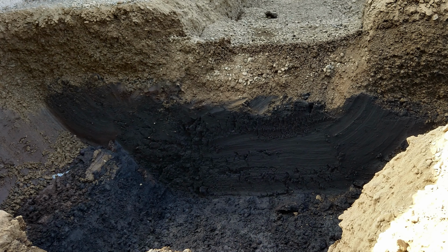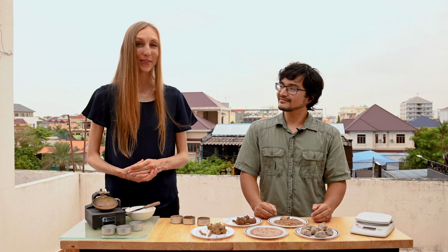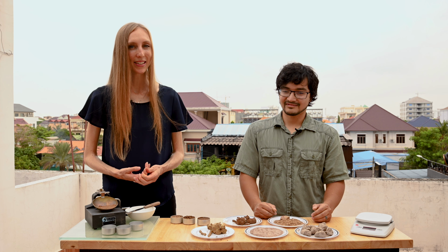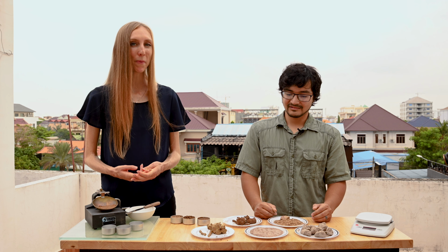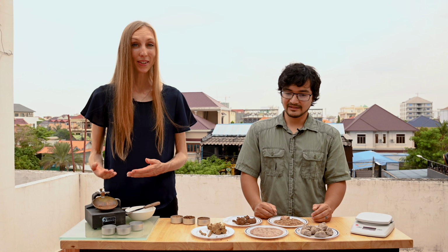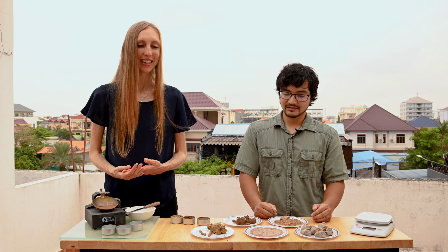We can also encounter a subgroup of soils called organic soils. These are typically fine-grained and formed by decomposing vegetation. They usually are a dark layer in your soil stratigraphy. So their presence can lead to unsatisfactory soil performance, including low soil strength and excessive settlement. So it's really important to try, while you're in the field, to be aware of this soil layer, to look for it, and to plan your design around it.